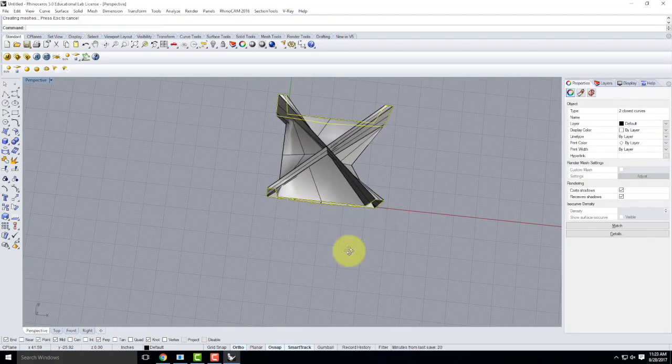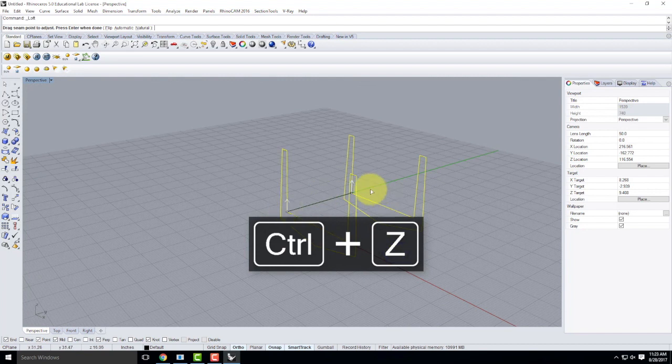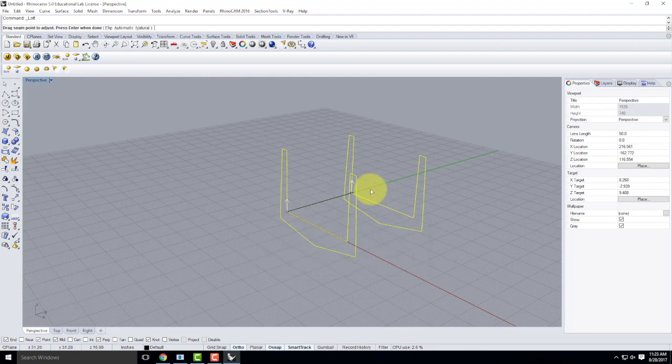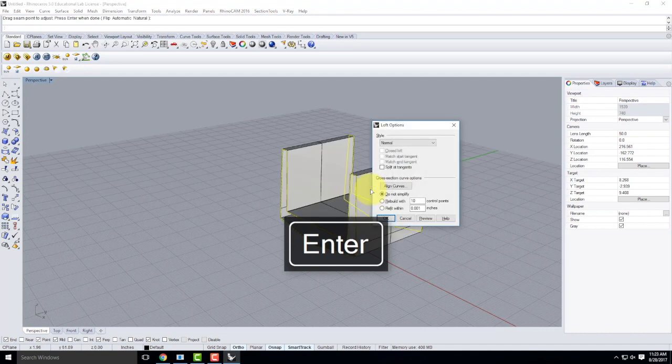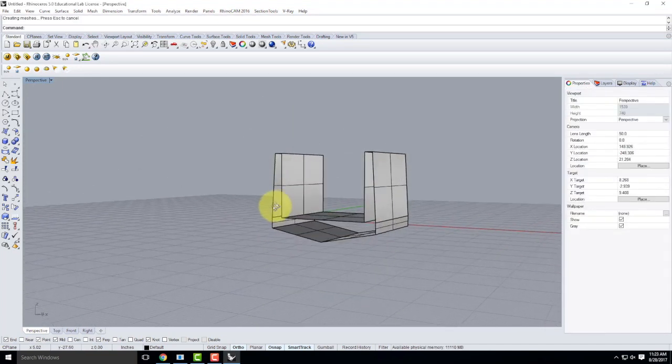So when you're doing a loft that contains multiple curves, making sure that the loft actually happens in the same direction across the same plane makes all the difference. So I like to at least point that out. You can, of course, explode and do separate lofts for each one. There's nothing wrong with that. You're going to get to the same spot. So there are my individual pieces there.